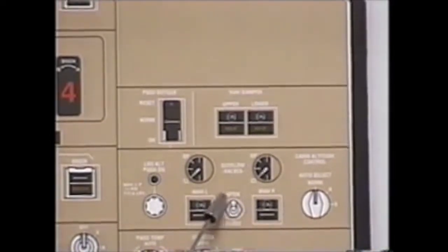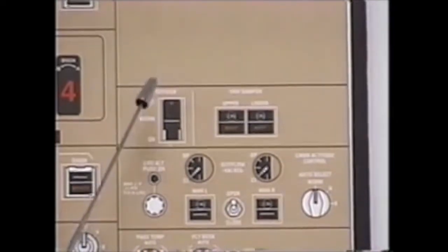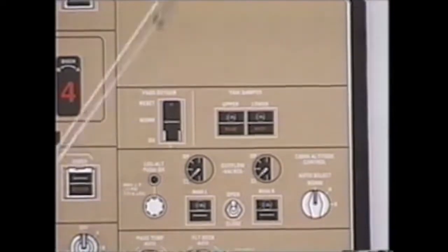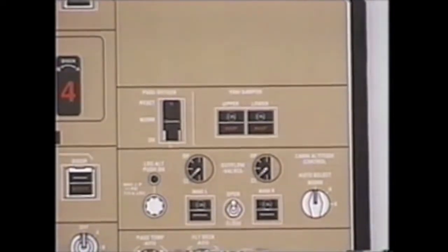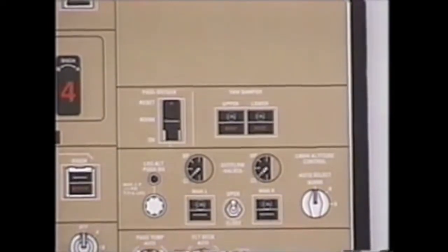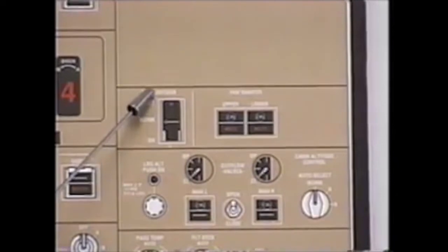Above your pressurization control panel is your oxygen control panel, 3-position switch, norm, on, and reset. This is the only switch required to be safetied during the cockpit setups. That would put it in a norm position. In a norm position, whenever the cabin altitude exceeds 14,000 feet, the passenger oxygen system automatically activates. Regardless of cabin altitude, if you reach up and select the system to on, the system will activate regardless of pressure altitude. To reset the system, you must be below 12,000 feet of cabin altitude. Momentarily hold the switch to reset.